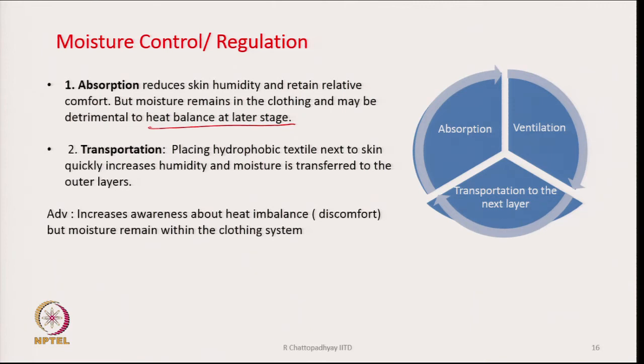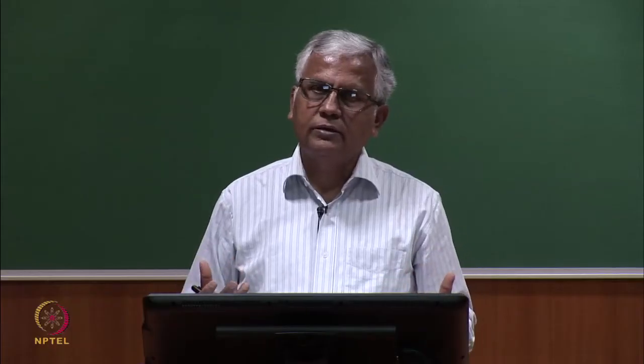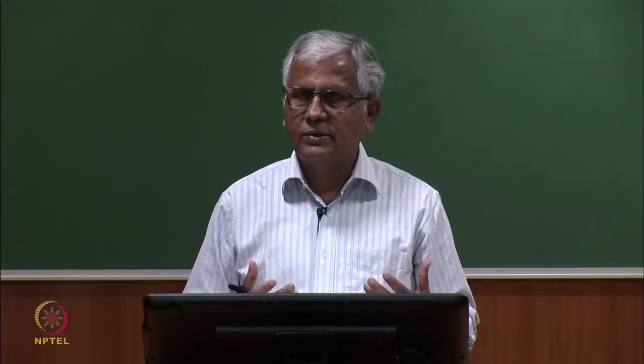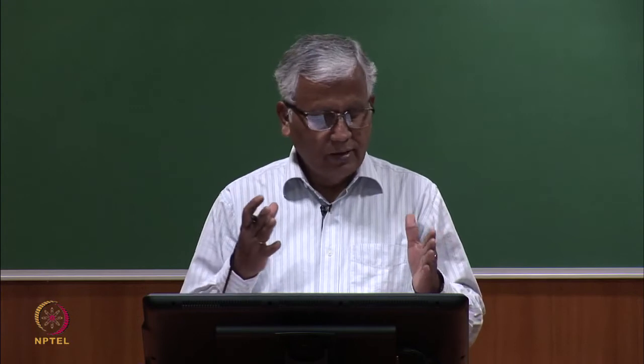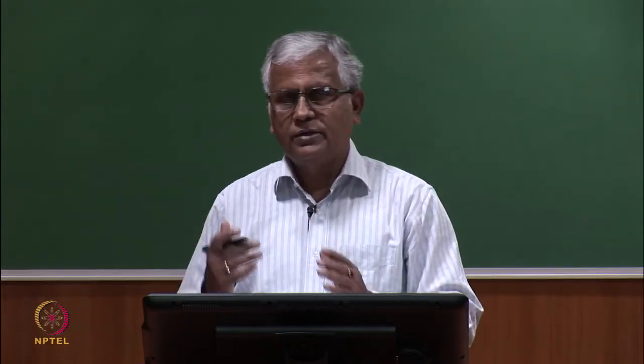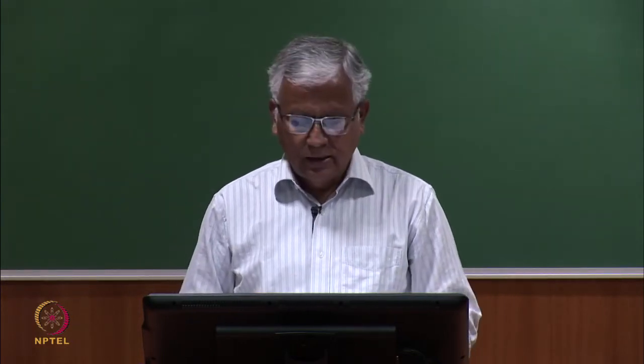Initially it may be helpful for some period of time, but when someone has to wear it for a long period of time, it may be detrimental, because it will hold the moisture which may get transformed into a liquid, because you will reach a saturation level after some time, and once the liquid formation is there, the insulation value will suddenly drop down, the fabric surface will try to cling to the skin, and discomfort will be there.